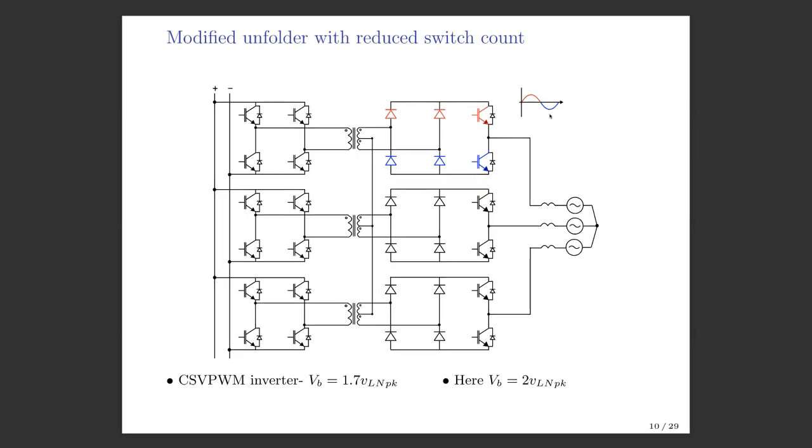So now we have this, but you see this solution has too many devices. It is a complex converter, right? So then can we reduce the number of devices? Yes, we can. So here is one solution. See, the DC side bridges are still remaining the same, but on the AC side, we had a full bridge and now we have a half bridge, but we still have 4 diodes here in every phase.